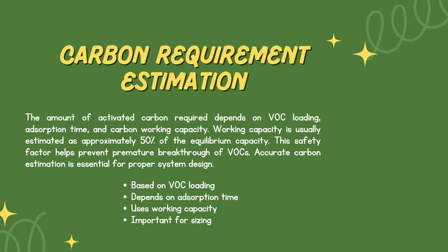For the carbon requirement estimation, the amount of activated carbon required depends on the VOC loading, adsorption time, and carbon working capacity. Working capacity is usually estimated as approximately 50% of the equilibrium capacity. This safety factor helps prevent premature breakthrough of the VOCs. Accurate carbon estimation is essential for proper system design.